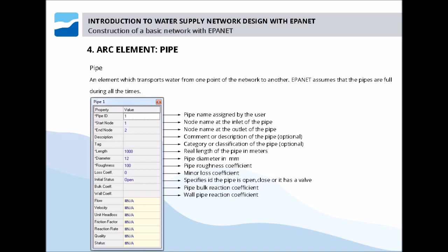The Darcy-Weisbach method is the most accurate one in theory. It applies to any fluid in any regime. And lastly, there is Chezy-Manning method, the most widely used, but generally for open flow channels and not so much for pressurized pipes.